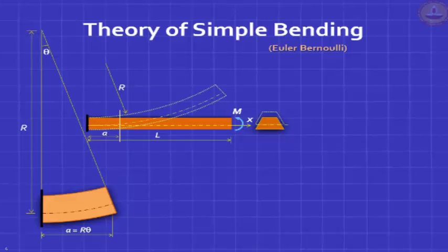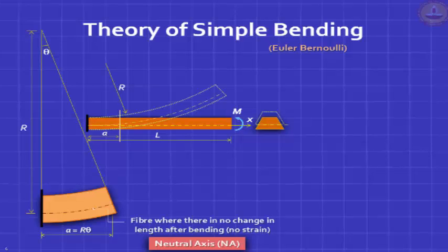You can clearly see that in this curvature, which is a sagging curvature, the layers above that chain dashed line, which we call the neutral axis, sometimes referred to as NA, where there's no strain and therefore no stress, will be subjected to contraction and a compressive stress, and the layers below will be subjected to elongation or a tension.